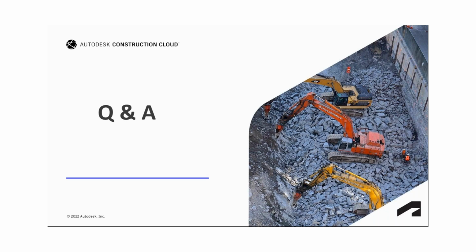It's not going to be Civil 3D, it's going to be just that published PDF, because the only thing that Takeoff supports right now is a PDF, a Revit file, and an IFC file. So that Civil file would need to be printed to a PDF, and that's exactly what I had with the AutoCAD files. They were printed as a PDF from the AutoCAD files.